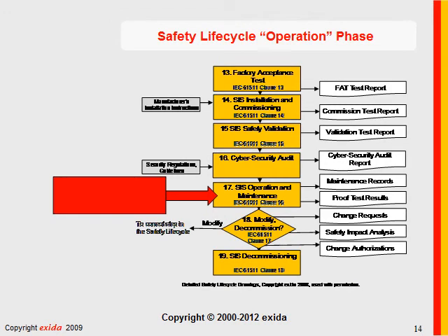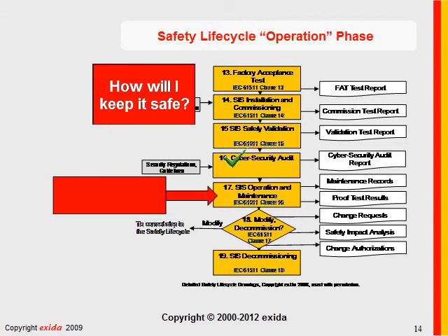Don't forget. All right, the last phase of the safety life cycle is the operations phase. Now, this is where we test our safety systems and then introduce them into service, including, by the way, don't forget that cybersecurity audit these days. Cybersecurity threats are indeed credible. Do you need any field failure data for this? I mean, yeah, I don't know. What would you use field failure data for?